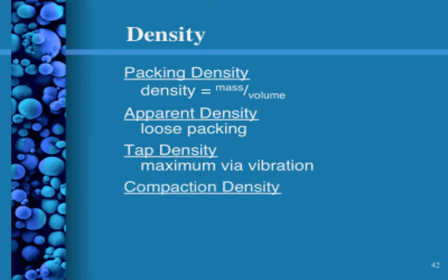You can take powder and apply pressure to it, and up to a certain point you can increase the density. Depending upon the initial density, the final density is going to change according to pressure. So that could be another way to define packing behavior. There's a limit, which depends upon the initial packing and upon the mechanical properties, how deformable the powder is. That's going to limit how much material you can pack.